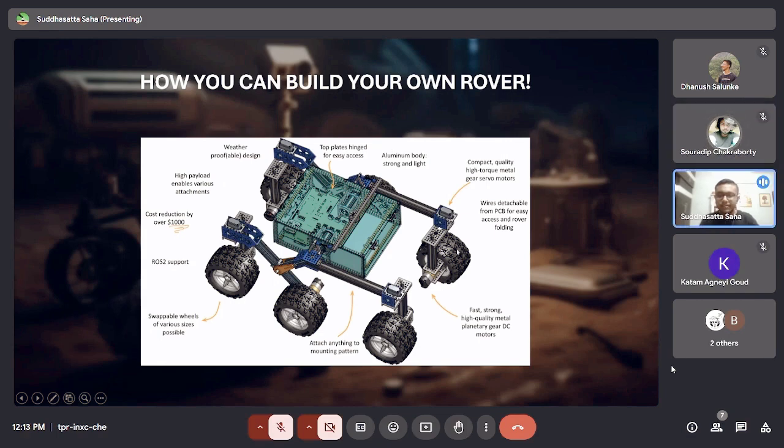So here you see how you can actually go about building. So you need to consider the various subsystems which I've already mentioned. You need to have some guys working in your electronics and computing domain, somebody who will build up the autonomous navigation module for you. You need to select a single board computer. For starters, you can use Raspberry Pi, or you can use Arduino, or for that matter, you can level up and use NVIDIA Jetson Nano, which is a single board computer for taking all decisions and all of this